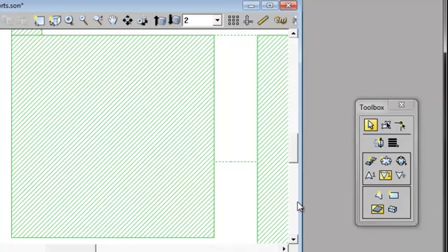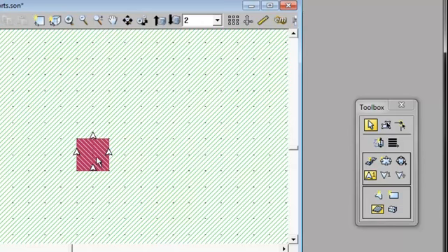So the first step is to create a via. I want the via to go upward, and so this little tool here will let us create a via that goes up, and then I'm going to create an arbitrary via rectangle. So I'll click into that now to enter the create via mode, and I'm just going to create really the smallest via I can, a really small one right there, and those little triangles there now tell me that the via goes up from this layer. Now you can see it's quite small.